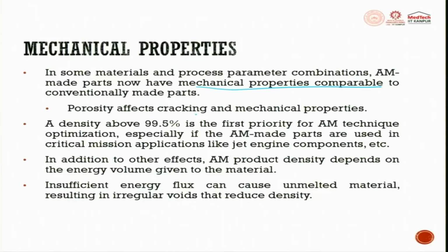Porosity affects cracking and mechanical properties. So this porosity today is avoided in a big fashion. This porosity could be because of thermomechanical properties of the metal powder and the laser process parameters. Since the characterization tools have gained a lot of importance and their accuracies have strengthened a lot, porosities can now be measured easily through